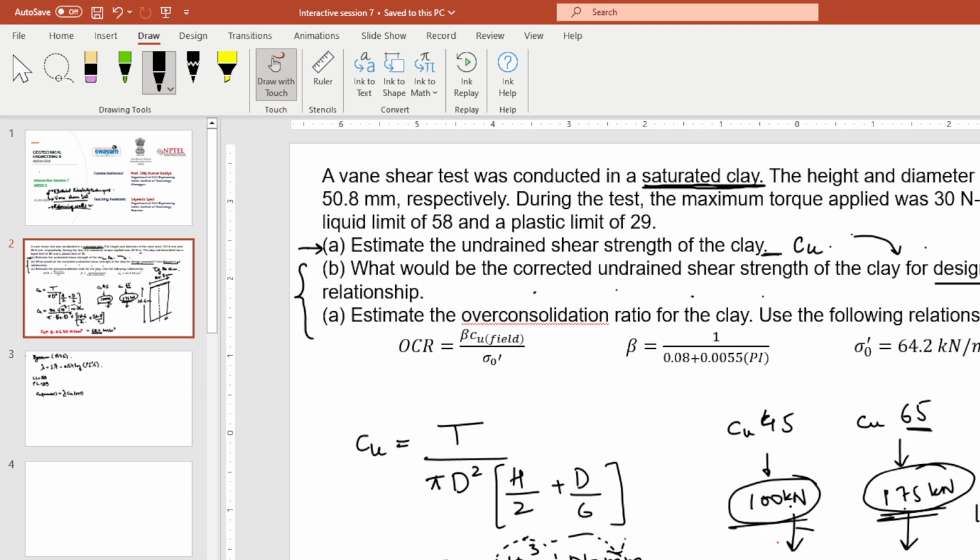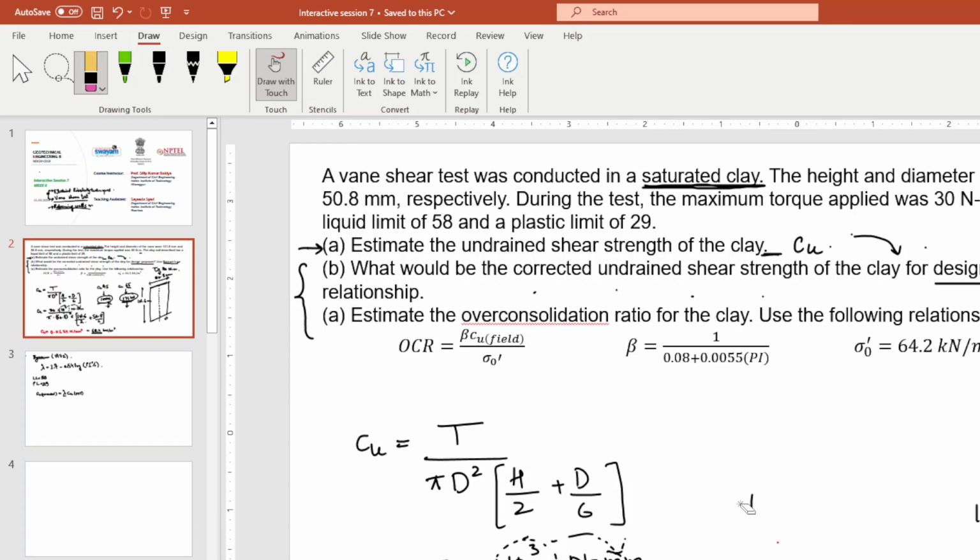What I'm saying is that it is the design philosophy that we don't want to over predict. This may be an over prediction. This cannot be the exact value, because when you go in the field, numbers rarely matter. What matters is whether your structure will hold or not. Maybe the real strength may be about 58 or something. So we want to reduce it a little because it is too high for design purposes. Do you understand what I'm saying?